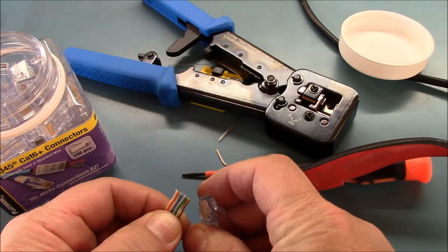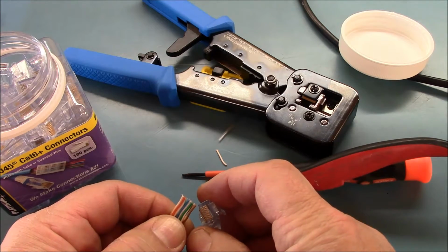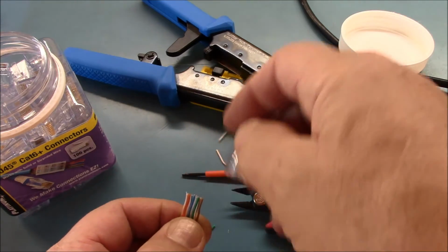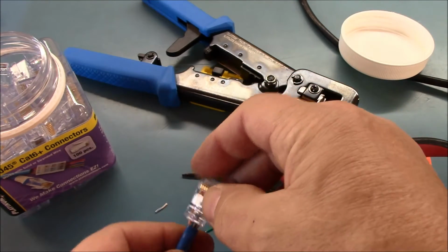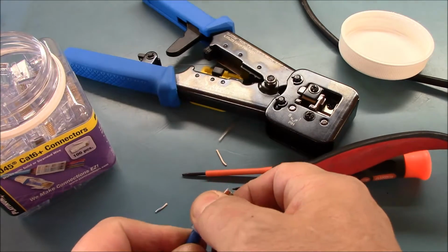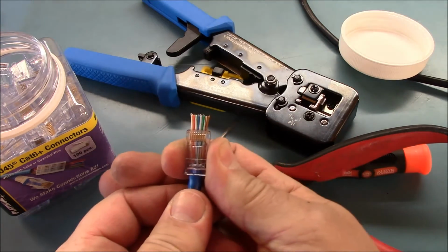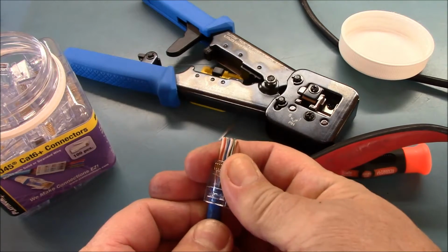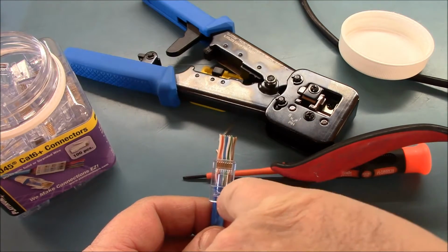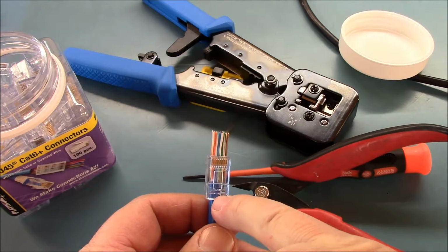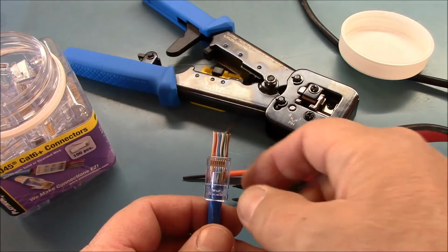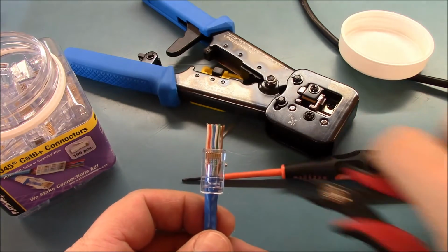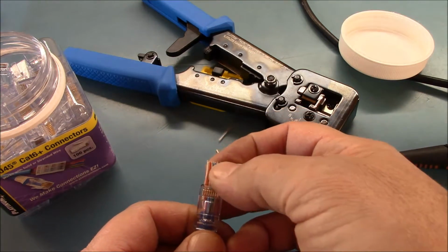Now these connectors actually have holes in the back side of them, which is the real key to the simplicity of this. So you're just going to stick the connector on it. You're going to have everything lined up, stick the connector on there, and keep pushing that cable into the connector until everything comes out the other side, and that blue sheathing is underneath this crimp point right there. When we go to crimp it with the crimpers, it's going to push down on that, and that's going to hold your wire.